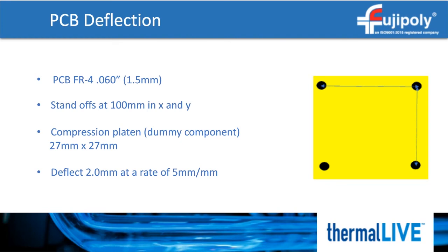There's always concern with localized stress on the solder joints. We often find the deflection of the PCB plays a big part in solder joint failure. The rigid solder joints cannot flex along with the very flexible PCB. This creates stress strains that can be difficult to predict, even with advanced modeling.